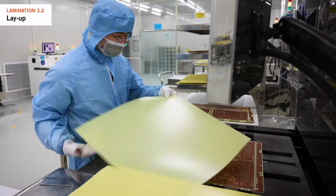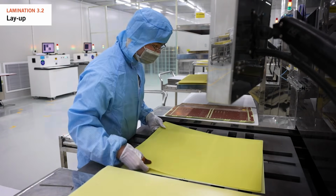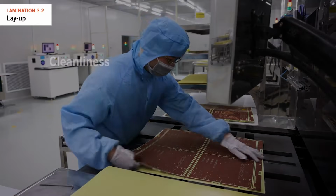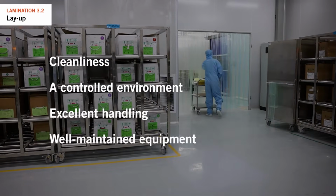The layup process is crucial for a quality multilayer, and it's a key focus during our audits. To get approval, the layup process must meet specific requirements, including cleanliness, a controlled environment, excellent handling, and well-maintained equipment.